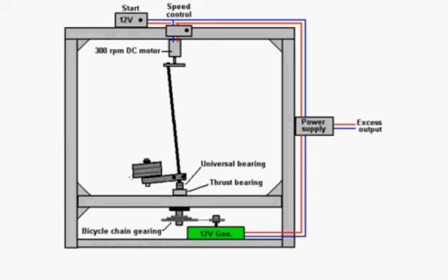But you can put a large weight, say the sort of thing that you get as a dumbbell weight, onto an arm, and with a very simple arrangement here, you can spin the motor, and that drives through a universal joint a shaft with, say, bicycle wheel gearing, that is a chain and a sprocket, to drive a 12-volt or other generator. And probably the best generator to use in something like that is one intended for a wind power system, because that's easy to do.